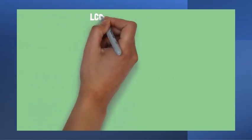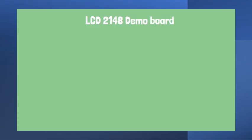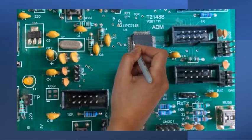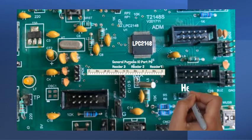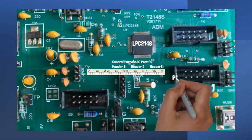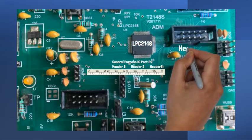Let us have a bird's eye view of our demonstration board. The demo board comes with an LPC2148 processor. The first 8 general-purpose I/O pins are connected to header 1 from P0.0 to P0.7. Header 2 terminates 8 more pins from P0.8 to P0.15.